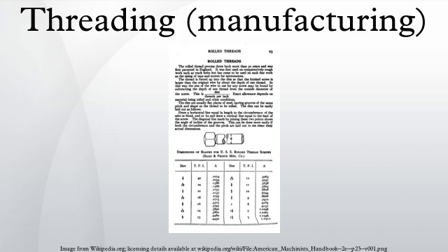This is plenty good enough for many applications, although it is not good enough for most commercial manufacturing. Higher precision methods are discussed below. Commercial-grade inspection of screw threads can involve most of the same inspection methods and tools used to inspect other manufactured products, such as micrometers, vernier or dial calipers, surface plates and height gauges, gauge blocks, optical comparators, white light scanners, and coordinate measuring machines. Even industrial radiography can be used, for example, to inspect internal thread geometry in the way that an optical comparator can inspect external thread geometry.